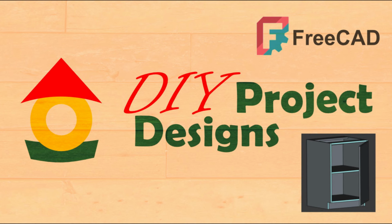Boards and wood products come in various quality levels. Even if they look similar, one plywood board may be superior to another if it was made from carefully selected, defect-free wood, used higher quality adhesives, or received more attention during production. This applies to all board types. Still, I've seen inexpensive particle board, the kind often overlooked, used effectively in interior design projects with impressive results. The most popular boards used for kitchen cabinets are either plywood boards or particle boards with a melamine finish on both sides.